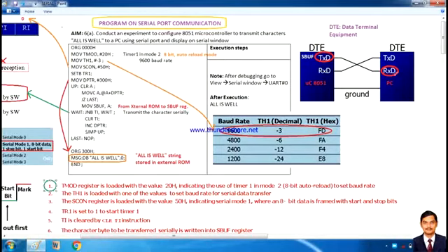So in order to create enough delay from the microcontroller to the other DTE, this is a must. Say your PC is working with a 9600 baud rate. To set your microcontroller at that pace, we have to use a particular timer to set the proper delay. So first I am using timer 1 mode 2 8-bit auto reload mode here.